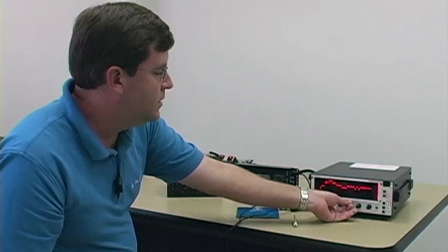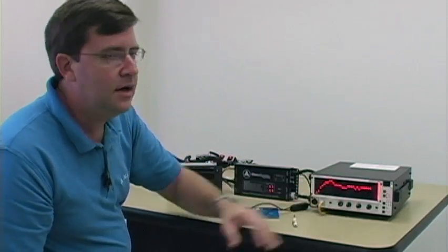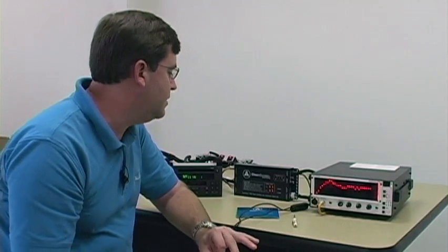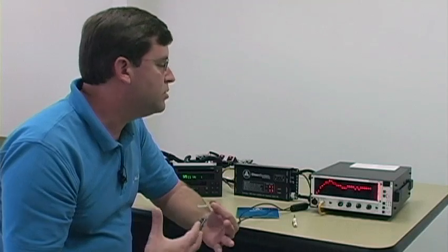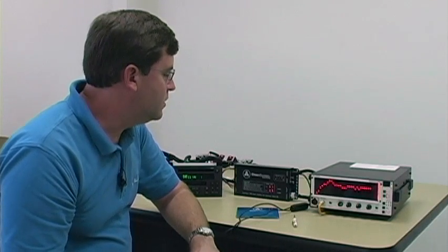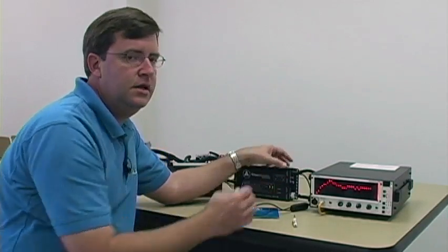As you can see, the CleanSweep was able to get all the dots on the screen, but it is not a flat response correction. So that's exactly what the code means, that partial correction was achieved, but it wasn't a completely successful calibration. Okay, so what do we do in this situation? Obviously, we have a problem with the signal that's feeding the CleanSweep not being full range.